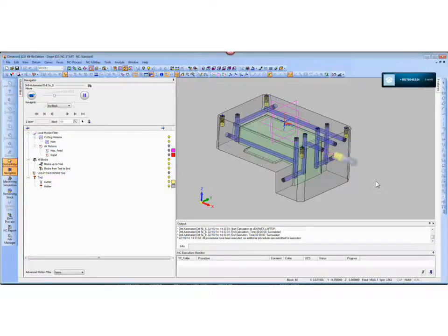So we can set a range, and we say whenever you encounter a hole from 421 to 422, this is how we want to process that hole. So it's not automatic programming where it has to fit the exact diameter and this has to be processed this exact way. It's more like we define a geometric range, and we say this is the process that we want to use based on it fitting within this range of geometry.